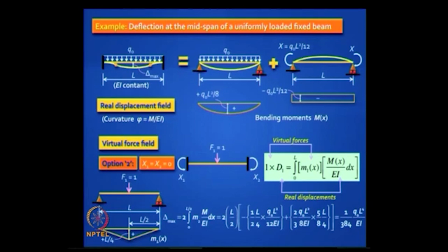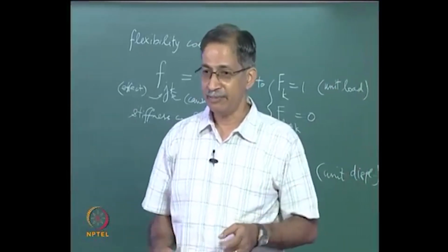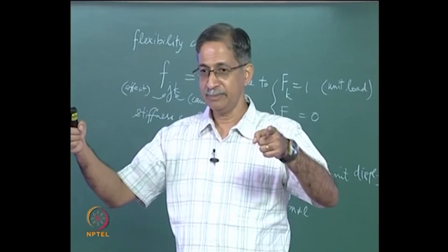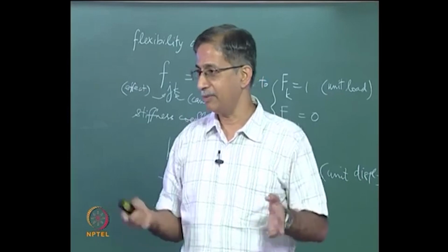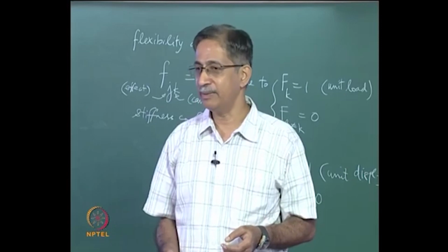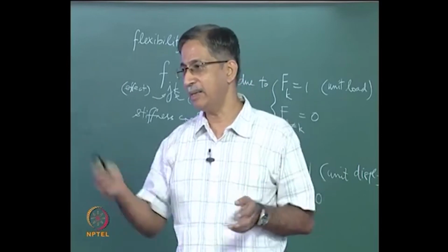This is really a mind blowing discovery. It shows the real power of the principle of virtual work, which means what are the implications of this? You take a complicated structure, a multi-storied frame, if you have the bending moment diagram in any one beam for example, that is enough for you to help you get the deflection in that beam, because you can strip it off from the rest of the structure and make it statically determinate, apply the unit load method. Similarly, we will see this later, you can find the drift in a tall building very quickly by invoking this method. So we will stop here, we will continue in the next class.